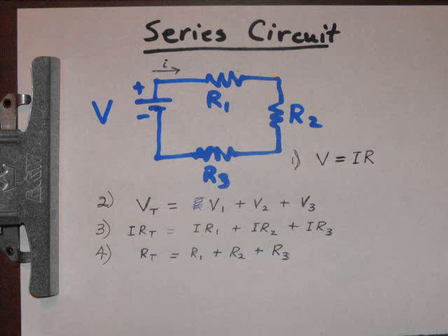If you have time, see if you can copy down this diagram. We're going to be coming back to a diagram very similar to this one, and we're going to have some resistor values. Notice that we've also put the current flow with a small letter i. It's a little bit better looking than the big I, so that's what they use. And there is one current that flows through a series circuit. It's always the same.